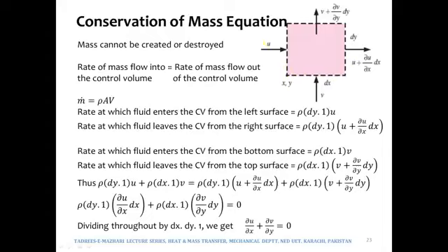Over here we have the velocity in the x direction as u, and when the fluid comes out of this differential element, its velocity would become u plus dou u by dou x times dx. This is the same thing that we have already discussed a number of times, and we discussed it in chapter number 2 while deriving the heat diffusion equation for the very first time, where of course it was not the velocity but the temperature, but the application of the Taylor's expansion is the same.